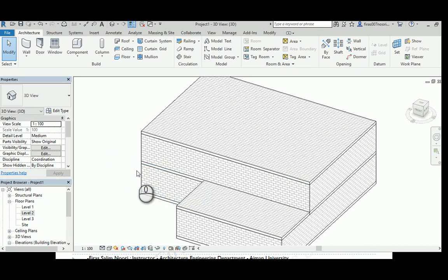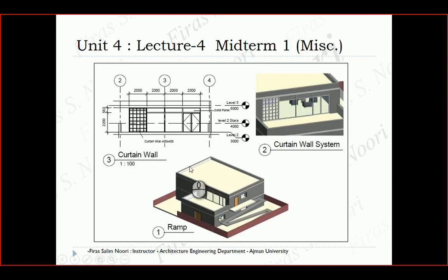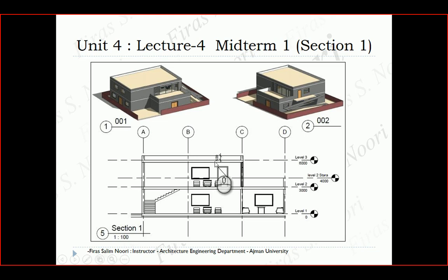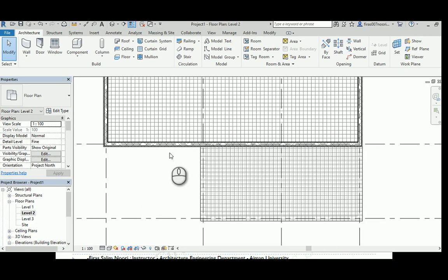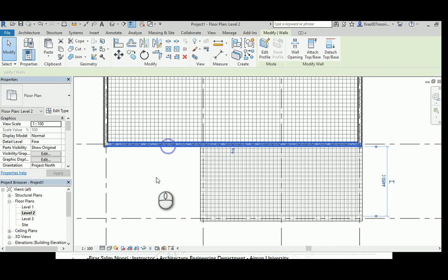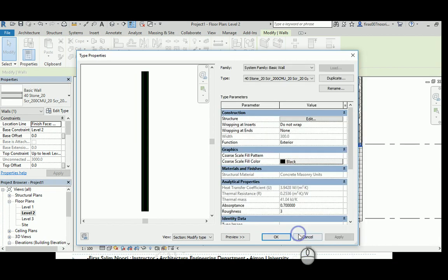Now parapets, in order to finish that job. As we can see in the 3D, I think it's a 1 meter parapet, and same thing here. Actually no, here it's 500. Yep, good. So again I will go to the second level here, and if you want, and that's a big if, you want to use this one again, you should change the type and duplicate it, and that will be finish 4 by finish 4, considering not to use the gypsum board outside, because it's really, really annoying, really wrong.